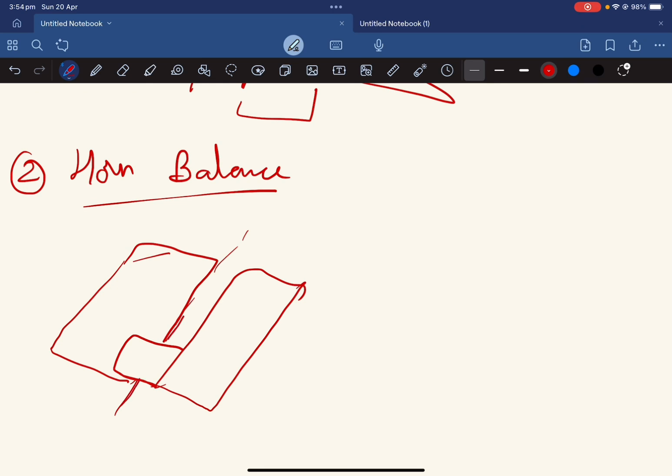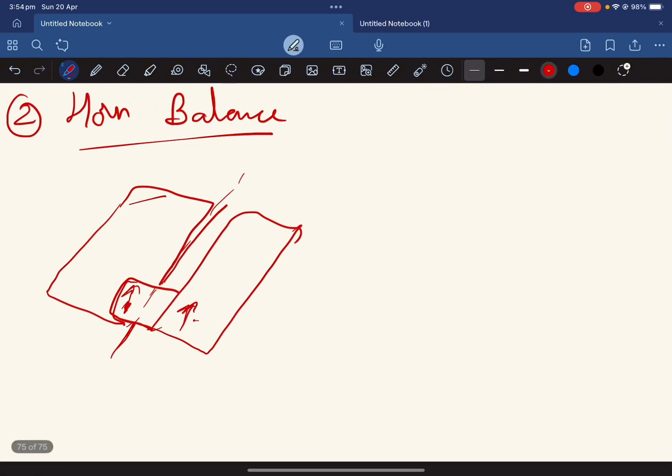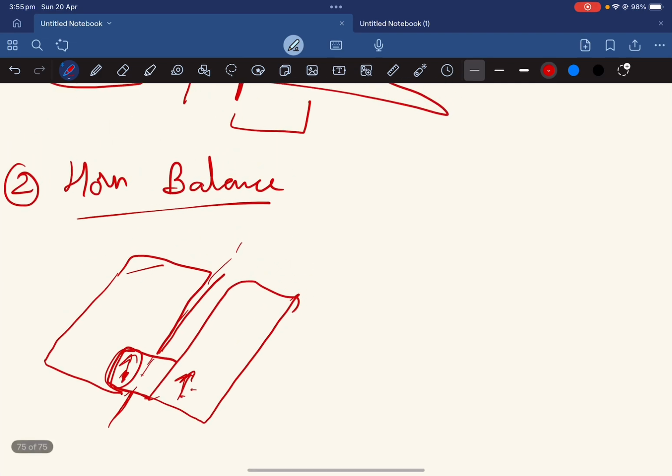So there's some force aft of it, and there's some force up ahead of it. The force being created ahead of it is going to be opposite to this, since it's on the opposite side of the hinge line, and this would reduce your hinge moment in a way.